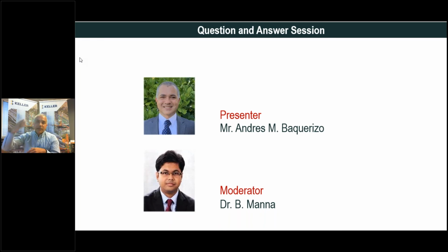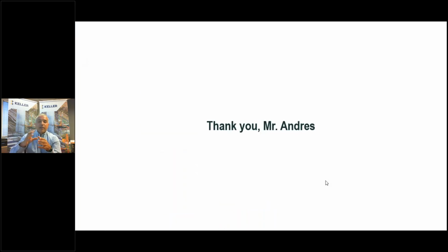For safety, on the top of the working grade, there should be an auger cleaner. When the auger is going through the cleaner, any soil that is there is going to hit the auger cleaner and be able to get out. There are cases where, if you take too long drilling a pile, the auger gets really hot and the soil attached to the flighting becomes really dense and stuck to it. That has to be reviewed on a case-by-case basis.